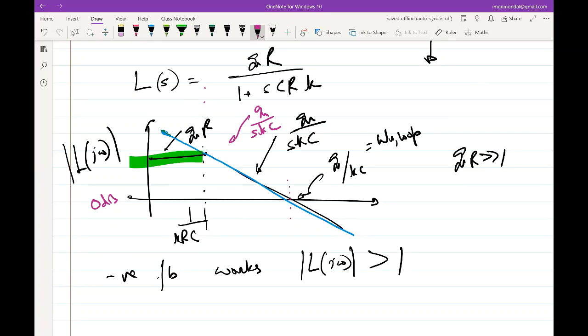Exactly, right? It will be stable. It will be constant till here, and I expect a gain of K, because that's what we have been doing for the last 5 weeks. And after that, it will drop off, at 20 dB per decade. But note that this will not be exactly K, because I don't have infinite gain.